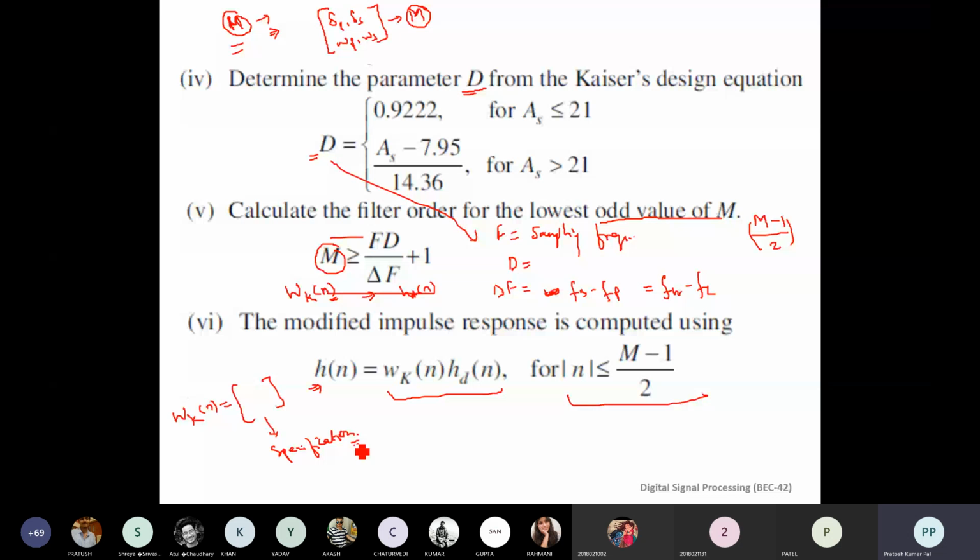find out that m value, which can be the optimized value. We can find m, the order of the filter, as an optimized value for including all the specifications given in the question. Whatever specifications are given, incorporating them, we will find the minimum possible value of m, because once we know the minimum value of m that satisfies the condition, we can reduce the complexity of the circuit.